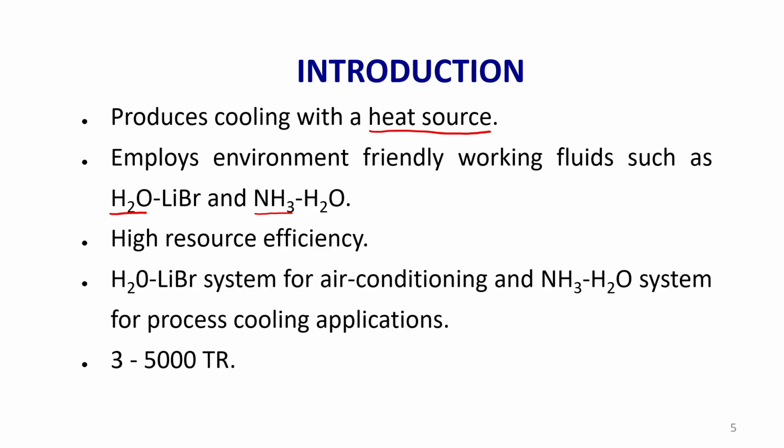But most of the hydrocarbon, CFC, HCFC or hydrofluorocarbon refrigerants have a single component only. So when I say water lithium bromide, water is the refrigerant, lithium bromide is the absorbent. When I say ammonia water, ammonia is the refrigerant and water is the absorbent.